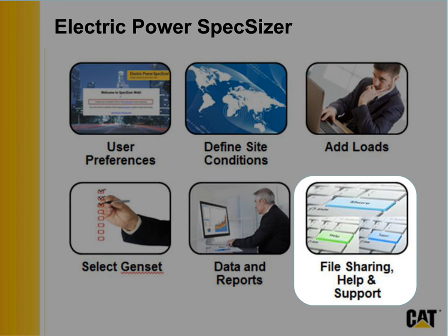If you don't do that, if you don't click the underlined rating, then you're still going to get the program best fit selected genset's reports. So easy enough. What we're talking about now is we've sized our genset. We know how then to access and print our reports.